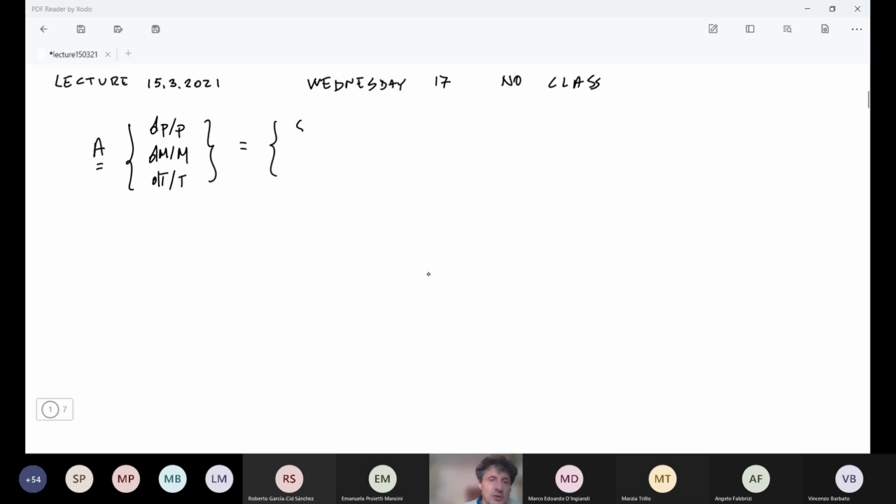And we have seen that this is governed by different terms, which we have called source terms or driving terms, related to our driving potentials, referred to as SC, SM, SE. This matrix A, I will report it here, is just a function of the Mach number. These are the coefficients: 1, 1, 2 delta M squared. Here delta is gamma minus 1 over 2. Then 1, 1/2, and 1/2.